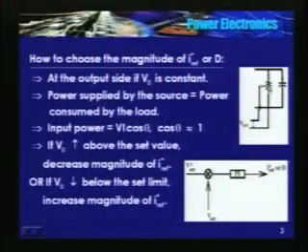I have put a big resistor here, a potential divider. There are other ways to sense the capacitor voltage also. A very crude method may be a large resistor here, a small voltage I will take. So this is V actual with respect to the negative DC bus. This is a reference value, so this is required, given by the application. I'll find out the error, which is nothing but V reference minus V actual.